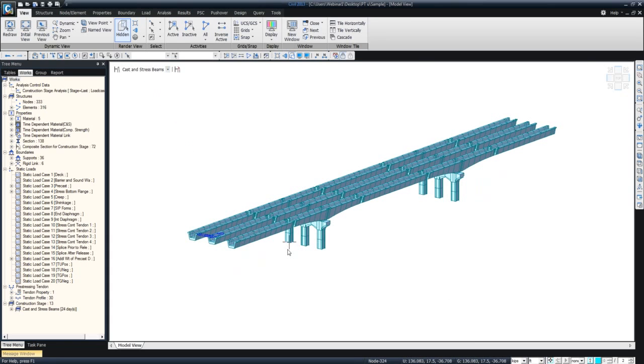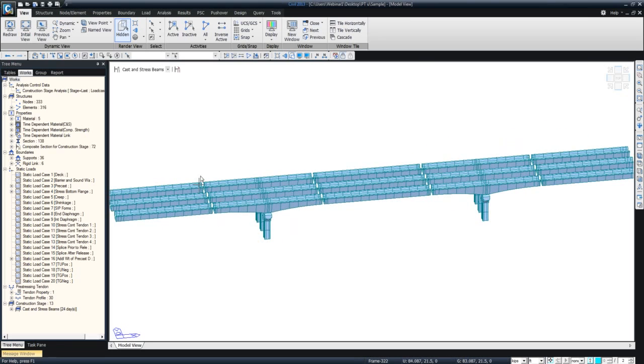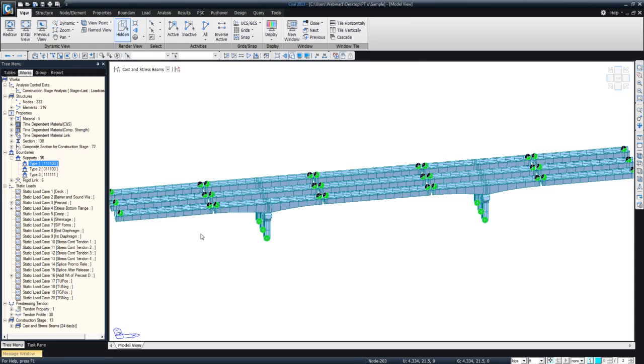Then we'll have the U-tub sections there without any cover, just the bare girders. And if you see right here, you can see the splice gap there. So the members are yet to be applied. So these girders, even though you cannot see the shoring here, it's a very popular method of using point supports at these locations. So if I turn on the supports, you can see there are some sort of supports applied at the splice location. So these point supports represent the shoring for you.